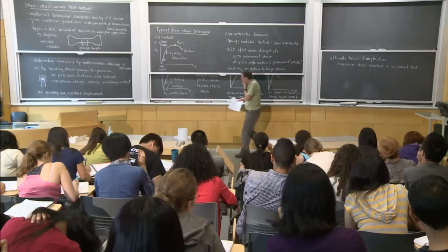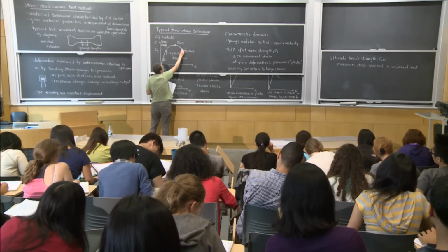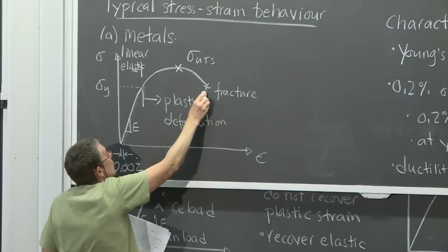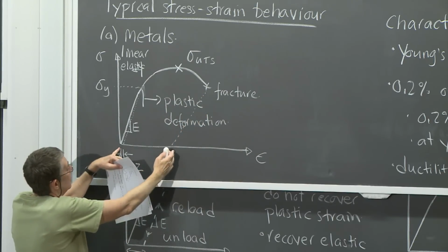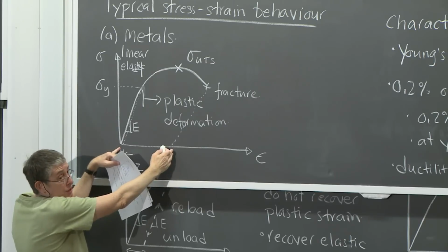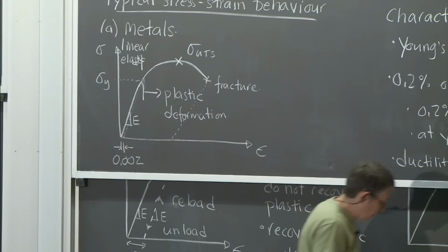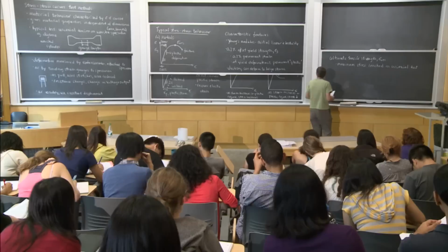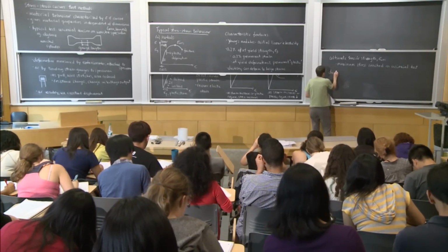And then the last thing is something called the ductility. And the ductility is if we went out to the fracture point here, and then we unloaded it back along our slope of E, then this total plastic strain here would be a measure of how ductile the metal was. Let me make another little drawing with that, because that one's getting a little crowded.